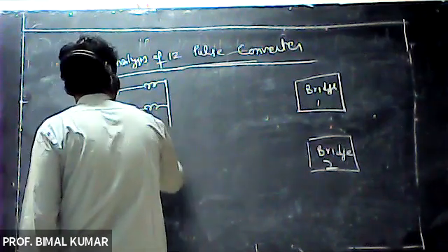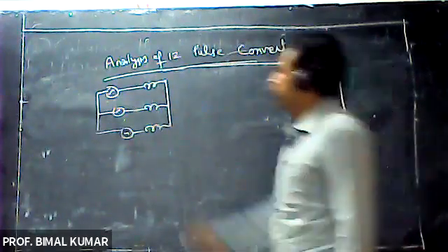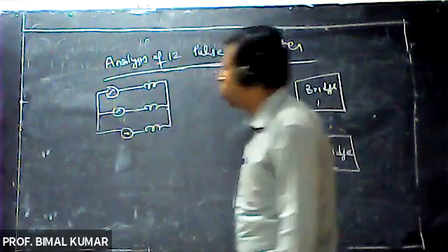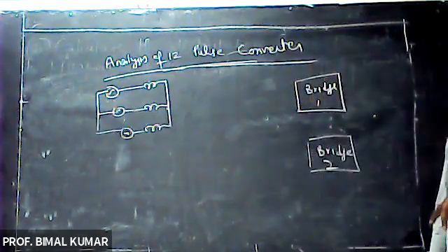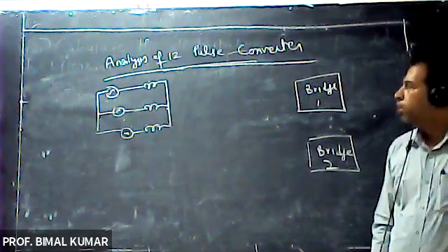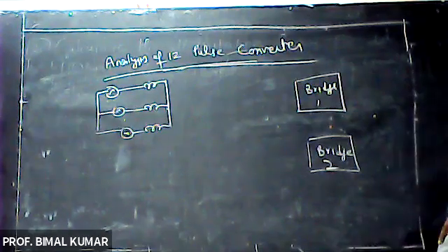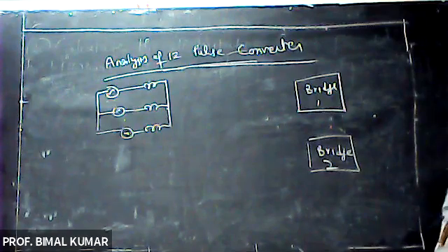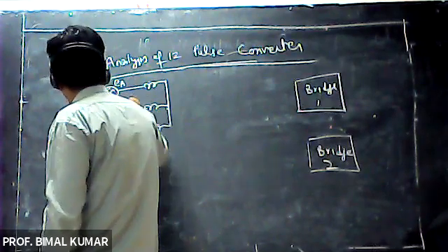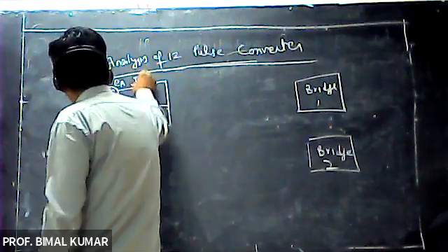See here. Now, because these are the three windings of the transformer, this will denote the input of the transformer, right? If either the starting or finishing terminals of all the windings are connected together, then the connection so formed is known as a star type connection, right? So this is your star type connection. Now here I am assuming that this will be your voltage EA, this is your voltage EB, and this is your voltage EC. In phase A, IA is the current flowing.